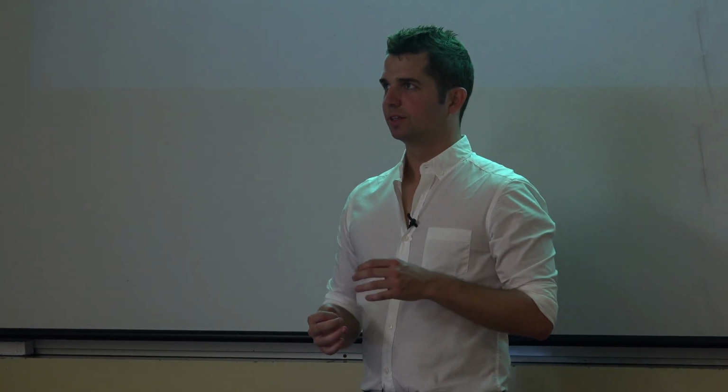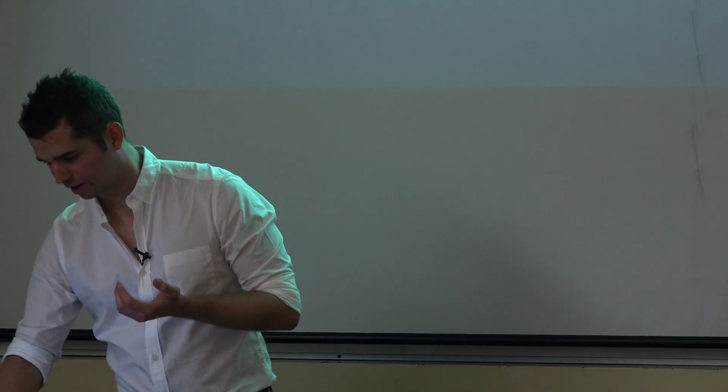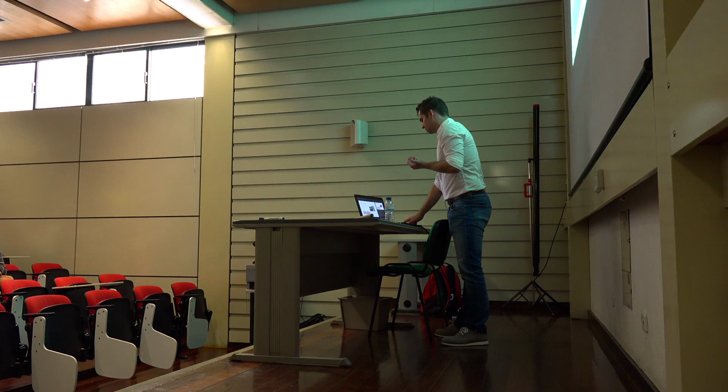Okay, so if I understand your question correctly, you're asking about design oriented to Monte Carlo worst cases or issues. Yes. So first of all, like I've pointed out before, one of the advantages of FinFETs is that you have better gate matching.